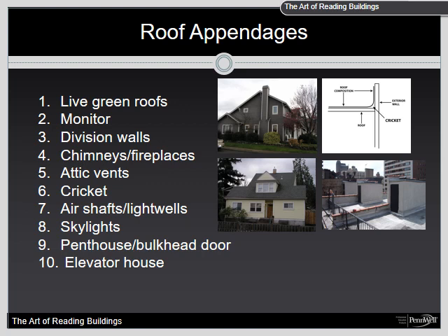So let's jump into division walls and talk about that for a second. Division walls are designed to partition a building and or minimize the horizontal extension of the fire and generally project at least 18 inches above a roof line. The important consideration to evaluate in a fire scenario is whether a division wall has been breached by the renovation, utilities, or for some other reasons.